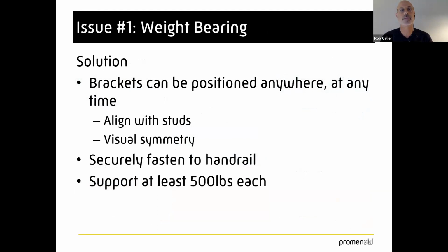We had to solve a couple of problems. The first is what David saw when they were installing: if they missed the stud or they missed the weld. They had all the studs measured, and they'd go to the shop and weld it, and it would be off by half an inch. Undo the weld, reposition it. So that's why we have this system where you can put the bracket wherever you want. What David wasn't thinking about was how you secure it to the railing. So that's where this cam head system came in, and it really just bites in there. So you can get it to any stud or move them just for some visual symmetry.